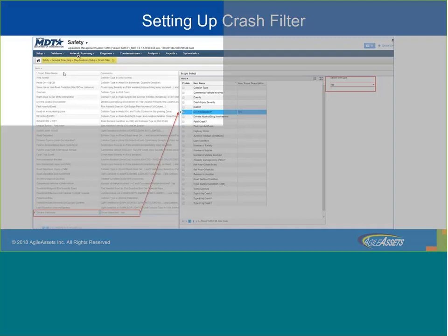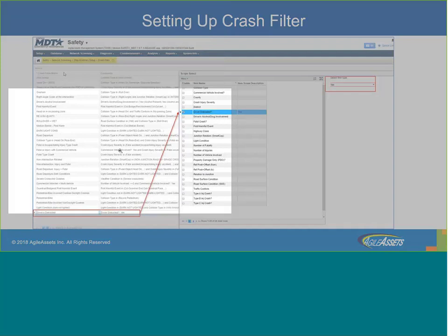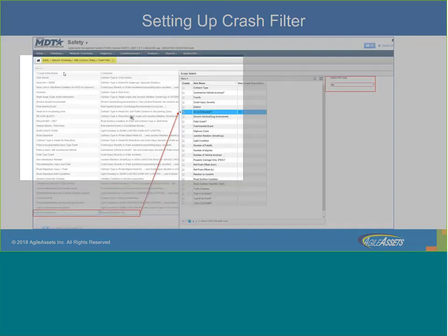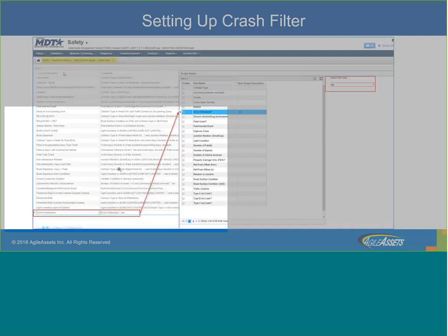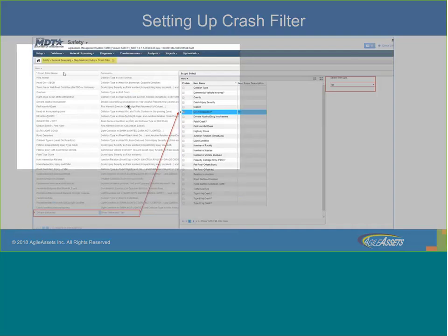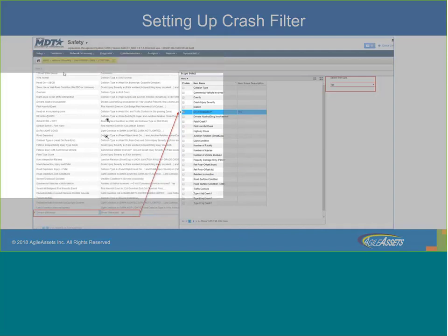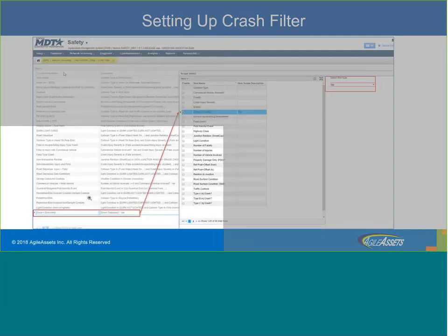So for this specific case, when you are running an analysis for distracted driving, we need to make sure that we create a specific crash filter for distracted driving. And what does this crash filter stand for? These crash filters can actually help us narrow down a specific type of crash. So you see that in our software, in network screening, we have a window where we can set those custom crash filters. In this specific case, I'm using distracted driving, whether the driver was distracted or not.